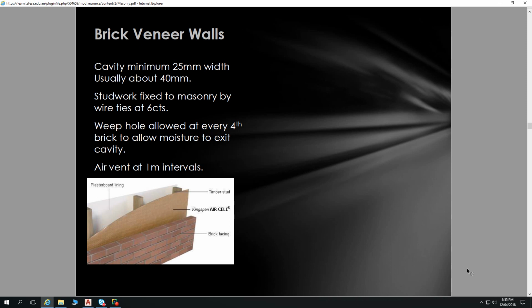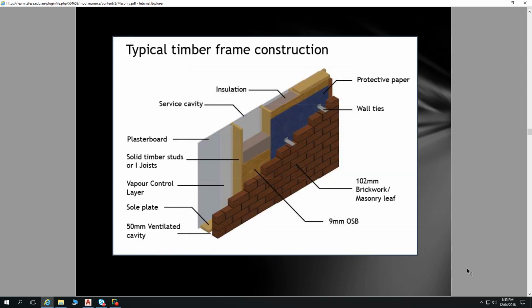But with the older brick houses that had raised suspended timber floors and strip footings, they had vent bricks at every metre intervals. And that's also typically how you can tell from the outside of a building what their floor height is. You look for the air vents and go, the brick course above that, that's where the floor in the house is.